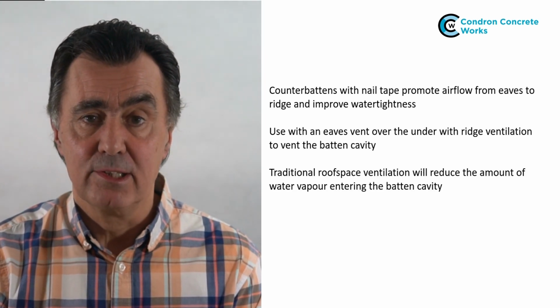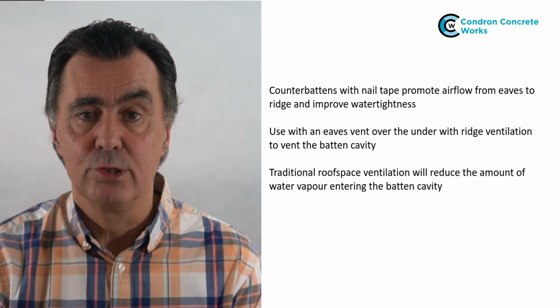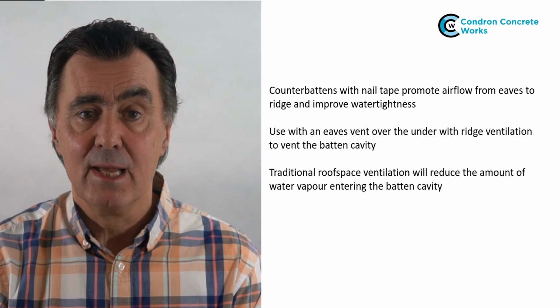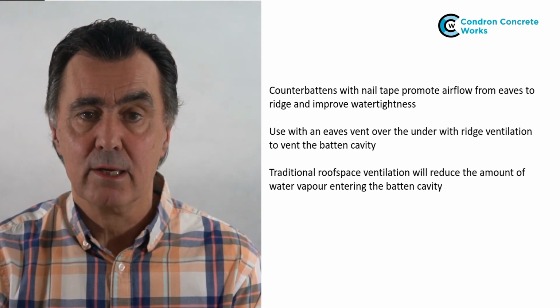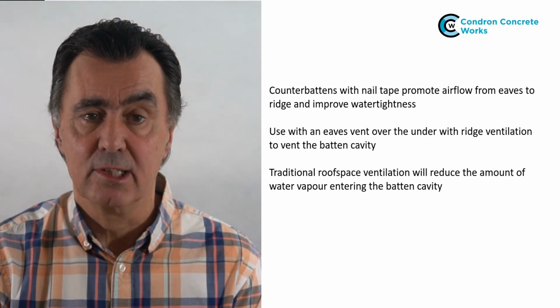Traditional roof space ventilation will remove the water vapour from the roof space and reduce the risk of efflorescence on the tiles, but depending on the type of underlay, it may not be recommended by the underlay manufacturer, and it will reduce the thermal efficiency of the roof insulation.